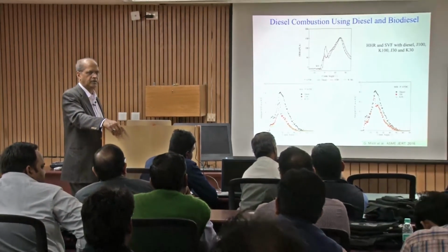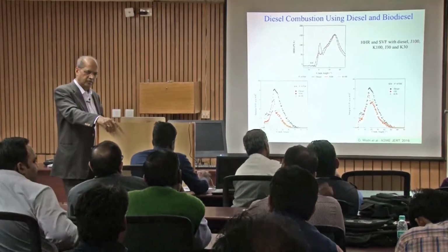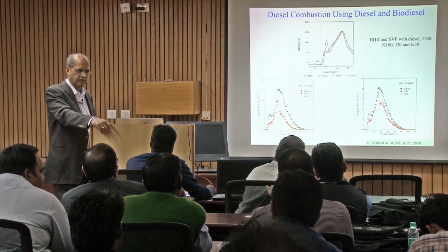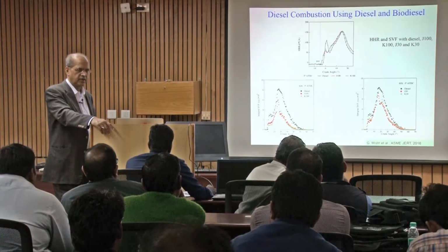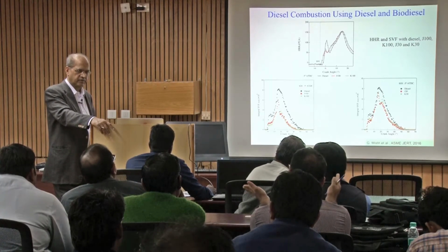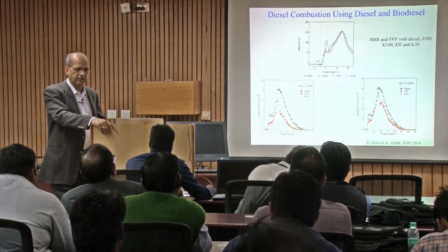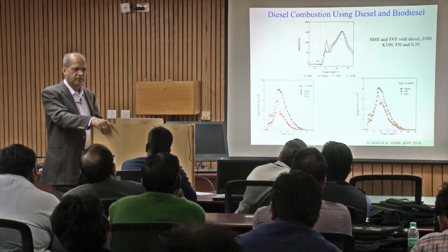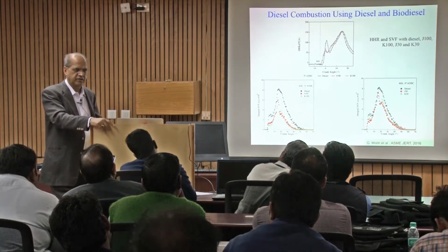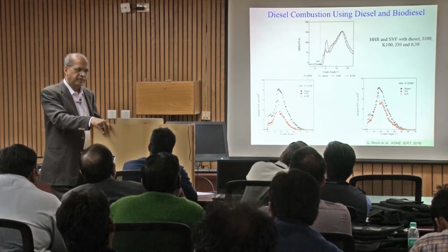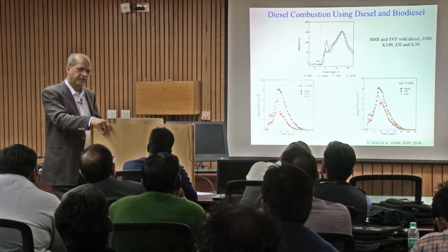If the ignition delay is bigger, then the temperature will be high because all the fuel will burn suddenly. That will also increase the temperature and NOx will be more. Oh yeah, that is known. But we said that soot depends on the premix. But if the premix phase combustion is more, then NOx will be more, because the temperatures will be higher. So it depends on the injection timing a lot. It means the NOx also depends on the premix phase. NOx depends indirectly; it mainly depends on the temperature.